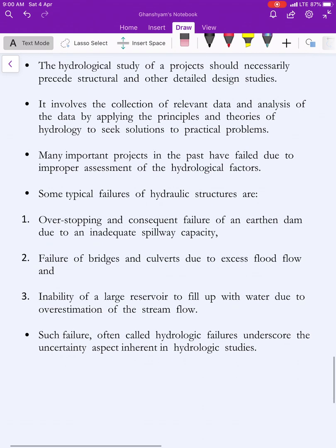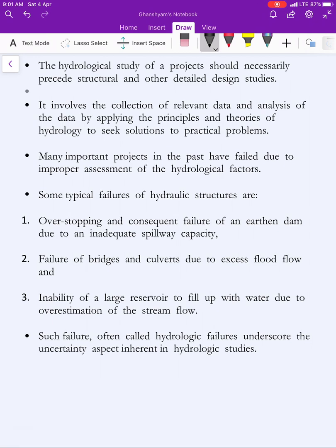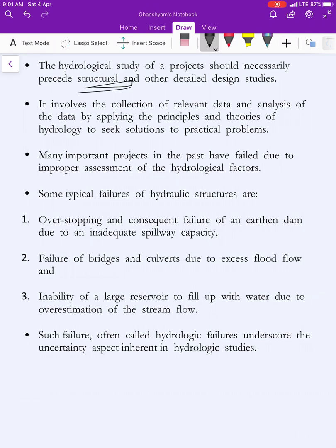The hydrological study of a project should necessarily precede structural and other detailed design study. So before designing the structural part, we have to perform the hydrological study, else the structure is going to fail. So what is this hydrological study?